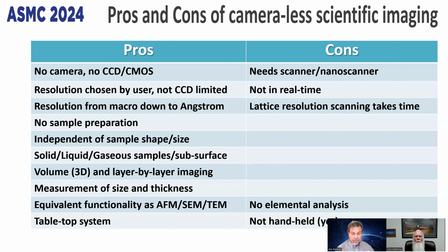However, we have to be cognizant of the pros and cons. The camera is shoot and record immediately. The terahertz or T-ray cameraless technique has some limitations, which is that it's not real-time imaging. We first scan it, and then the scanned intensities are converted into an image. The image can be made in many different ways because of that.